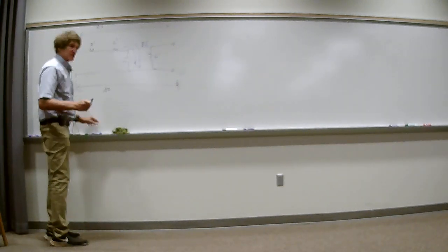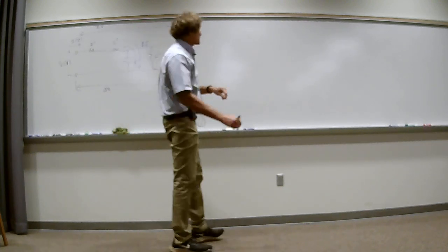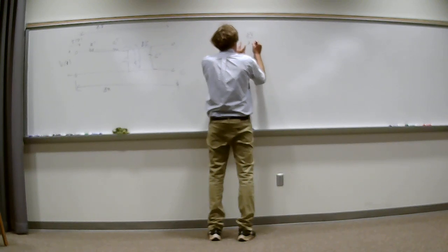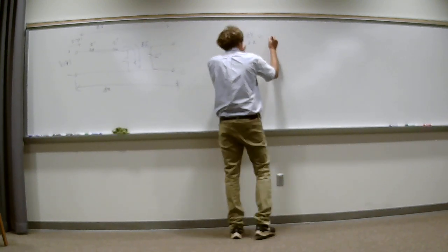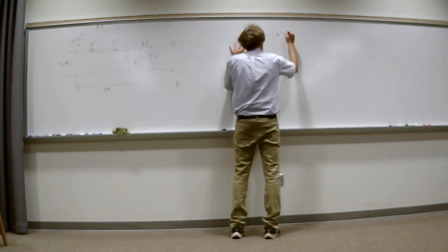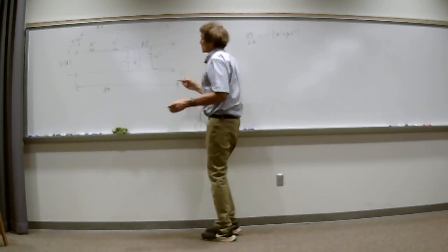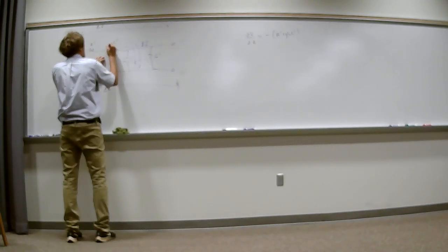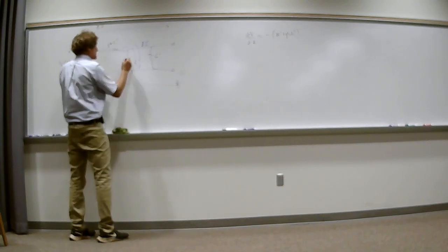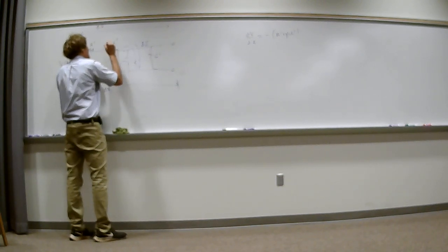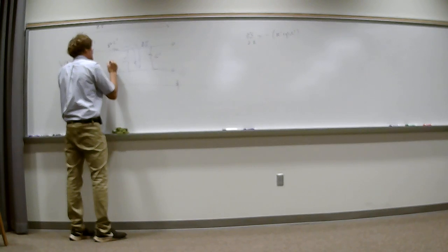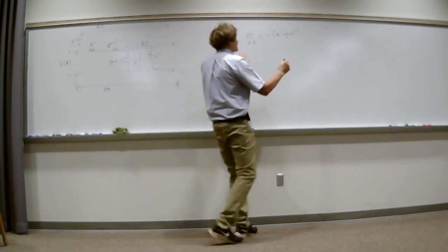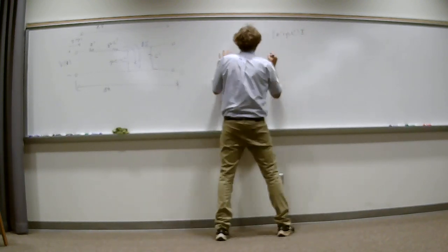So from this, I fashioned two equations. The first was that the rate of change of the voltage with respect to Z, and we are in the phasor domain here, was equal to minus R prime plus J omega L prime, because we're going to work in the phasor domain, so this impedance becomes J omega L. I might as well put it down here. And by the way, this conductance becomes, or I should say its admittance would be equal to J omega C right here. And when you do that, you got this times I. And that's the first one.